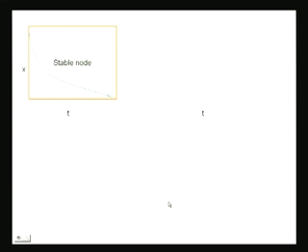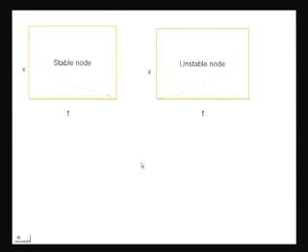This is the first case, where the real part is negative and the imaginary part is 0. In the second case, the real part is positive and the imaginary part is 0. In the first case, as you see, x decreases; x is a deviation. You gave a little perturbation, started with a little deviation at t equals 0, and the deviation decreases with time and goes back to the steady state. At 0, at the bottom of the axis, is your steady state value. You increased it to this extent and it goes back to the steady state value, fine. So, that is why this is a stable node.